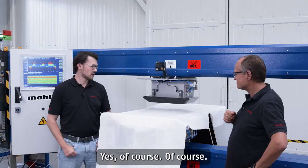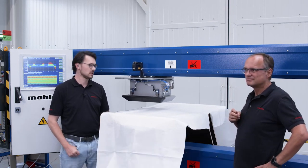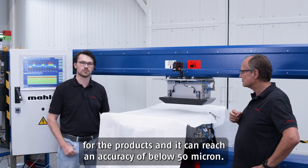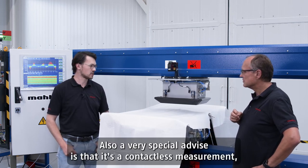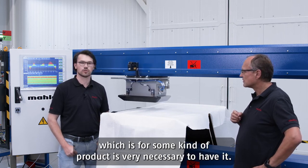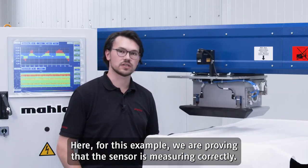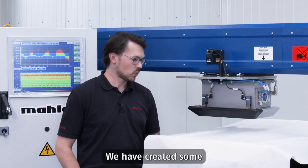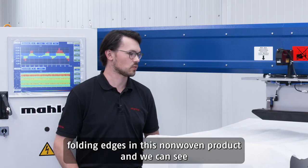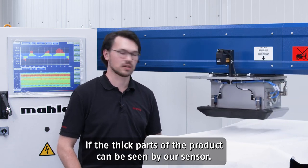Yes, of course. The basic information is that we use this kind of sensor mostly for plane surface products and can reach an accuracy of below 50 micron. Also, a very special advantage is that it's a contactless measurement, which is very necessary for some kinds of products. Here for this example, we are proving that the sensor is measuring correctly. We have created some folding edges in this nonwoven product so that we can see if the thick parts of the product can be seen by our sensor.